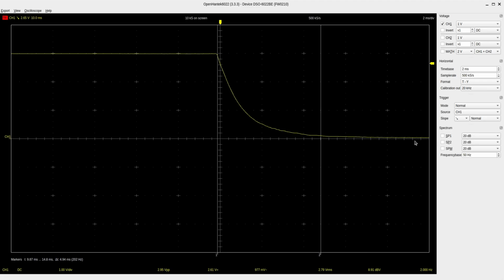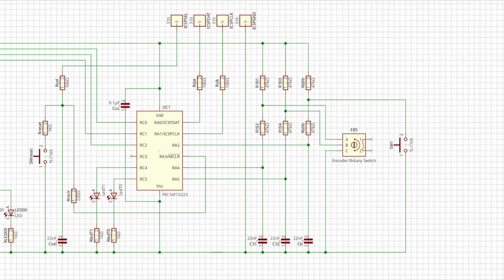Now that was very deliberate because we wanted to debounce this button, or prevent rapid changes, to accommodate for any sort of hardware deficiencies in the switch. So we're not going to be covering debouncing in this episode. What's important to note is that it takes time for it to settle at the new voltage. And on the scope, we can see that that voltage is nearly 0. But it doesn't have to be 0. I could change that voltage by adding a resistor into the circuit, such as right over here.